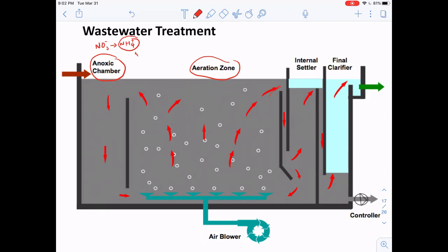And then by these baffles or channels here, the water will further flow through, to give it a longer residence time so that particles can settle down. And then we're able to get cleaner water from these different channels. So you can see that it needs a relatively longer residence time in order to remove these contaminants from the water, right? So in this way, we can also treat the water quality.